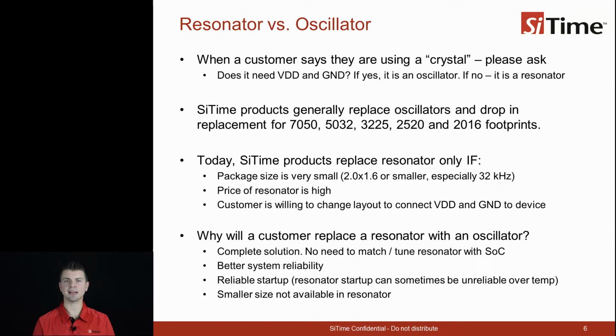As was discussed on previous slides, the clear distinction between crystal resonators and crystal oscillators is passive versus active component. Oscillators are a complete circuit with all oscillator circuit components integrated into the package. Therefore, the oscillator requires a power and ground connection on the printed circuit board. By contrast, a crystal resonator is only one element of the oscillator circuit, namely the high Q reactive element. Therefore, the crystal resonator needs to be driven by an amplifier and may also need an additional 2 capacitors in the case of parallel resonant crystals. Normally, the amplifier is integrated into the IC, which is connected to the crystal.